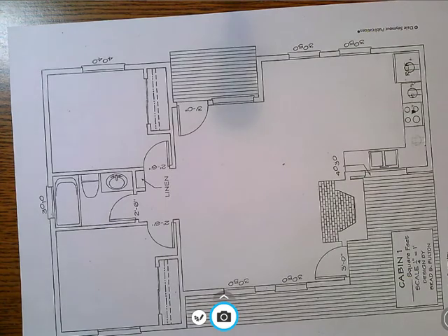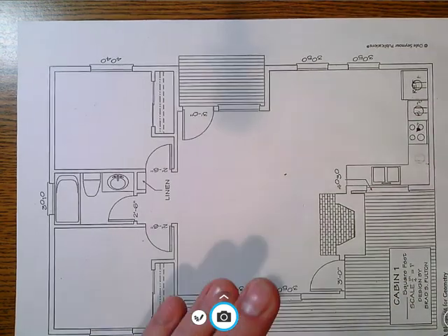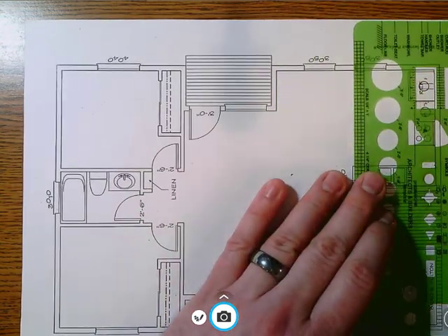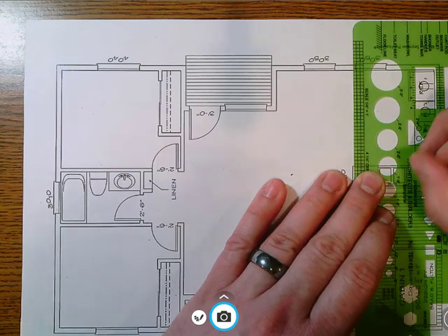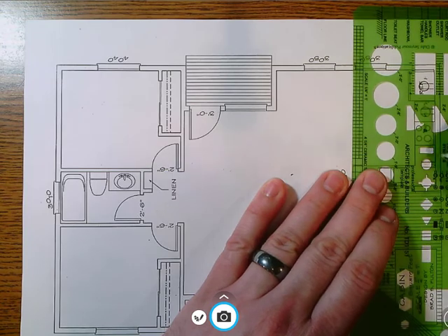That's the 2-foot mark. And again, the reason I'm doing this is if I place an outlet here, this 2 feet along the countertop will be covered by an outlet here, and this 2 feet will be covered by an outlet here. So if I strategically place this outlet in the middle of this 4-foot section of countertop, then this would be to code.